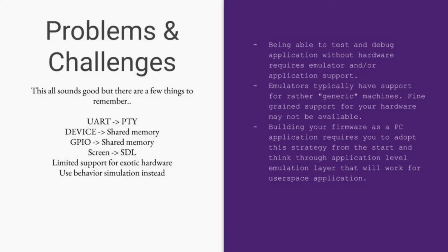So obviously the best method is to have the actual hardware and to debug it over JTAG, because that gives you maximum flexibility. You're actually running on the chip, and you can step the program on the chip. So all the details of the program state are fully accessible to you as they are accessible to the chip. So you're seeing the same things. If you're doing emulation, you would have to cut things down a little bit and focus on the higher level logic of the application instead.